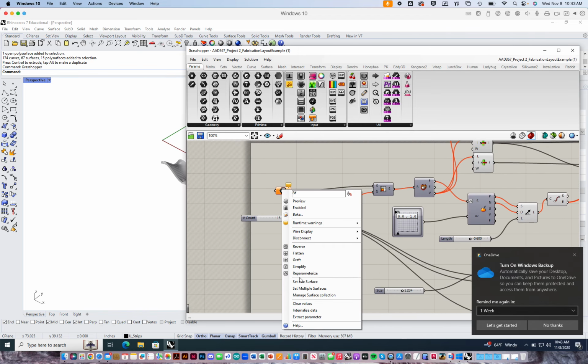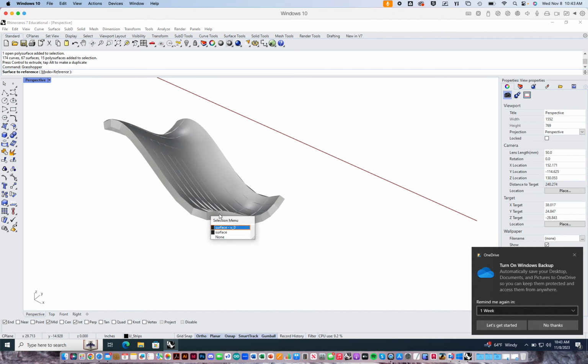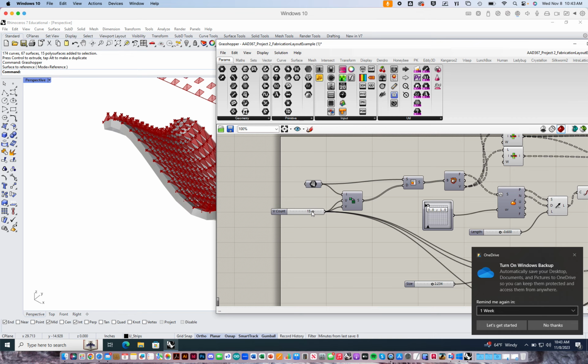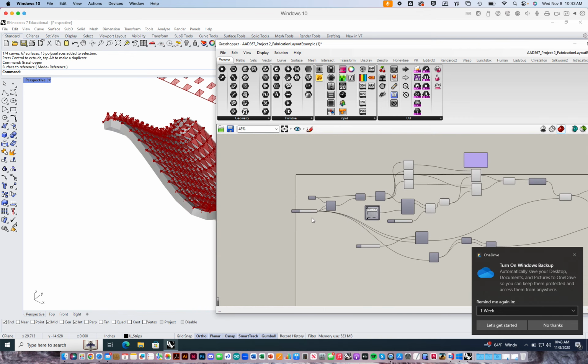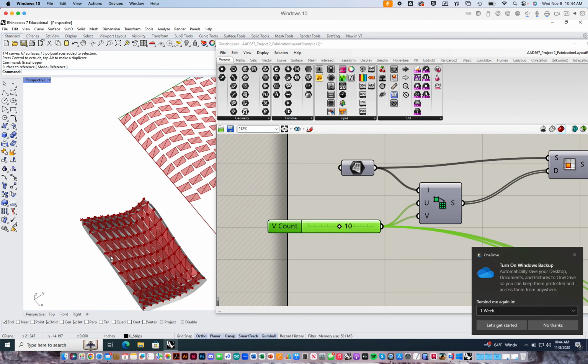The ingredient is the grid shell surface. So set one surface, just like you guys have done. Surface, there we are. Okay. Now it's dividing this thing 15 by 15, which of course is going to be a mistake. I have 10 by 10 cells with this structure, so I want to make sure that this matches that. So if I've already picked 10 by 10, then I'm going to come back here and make this 10 by 10.